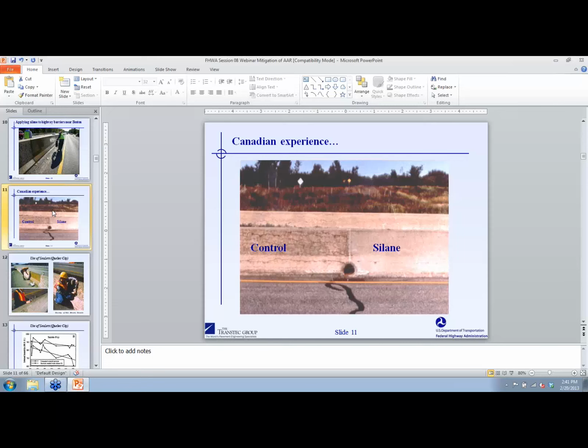Yeah, in all of our field trials, pop-outs were not really a main issue, but we have seen them in other pavements, and also in residential environments, around swimming pools, etc. So, certainly applying silane, trying to dry the concrete out, and improving drainage away from the pop-out region could potentially help, but that's about all we could offer at this point.